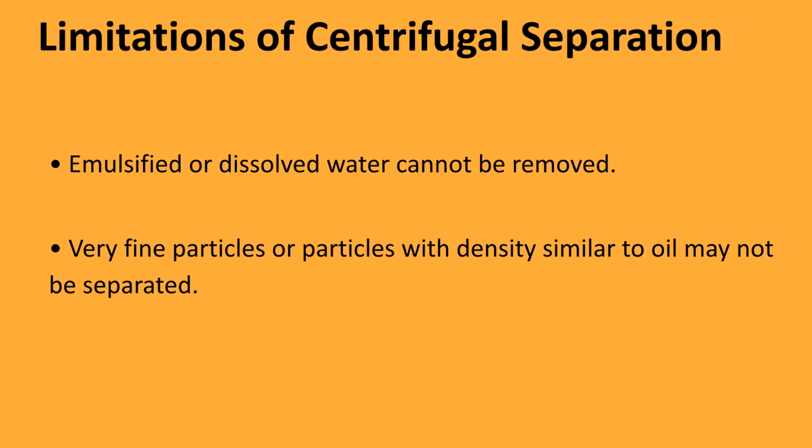Finally, we must recognize the inherent limitations of centrifugal separation. Specifically, these systems cannot remove emulsified or dissolved water. Furthermore, very fine particles or those with a density close to that of the oil may remain in the system.